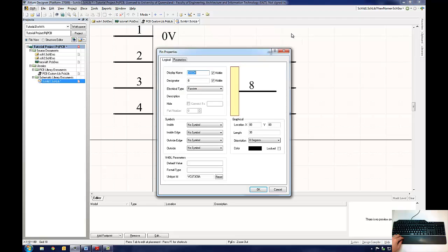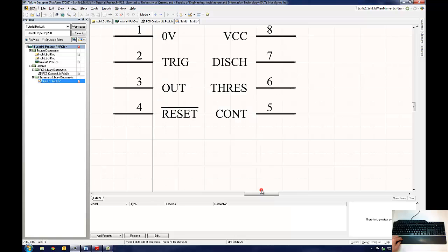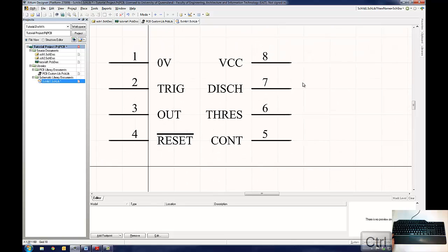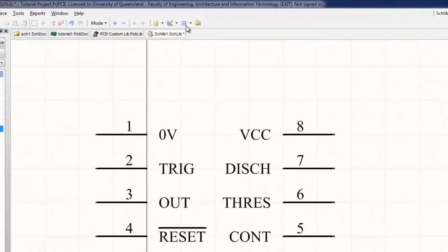Once all the pins have been placed in appropriate positions and labelled accordingly, the user should draw an appropriate symbol to represent the component. Many of the basic electronic components have standard symbols which should be used where appropriate. Microcontrollers are generally made up of ports, lines, and power ports. It is sometimes useful to collate these pins into their various ports even if the pin numbers do not always flow consecutively. Most microcontrollers can be represented by a rectangular block.